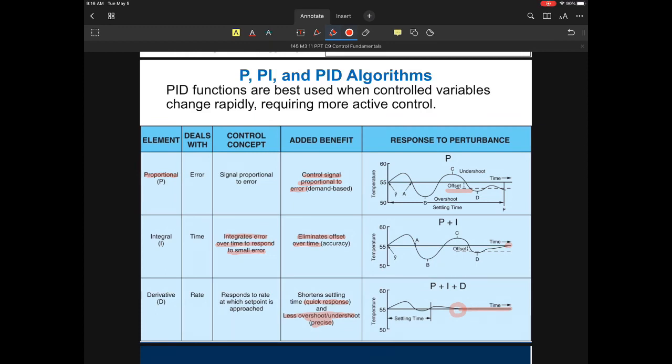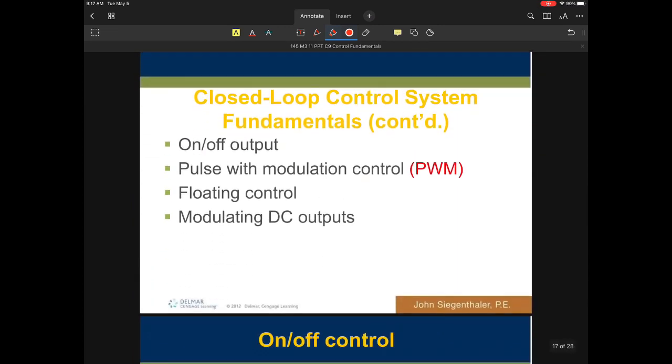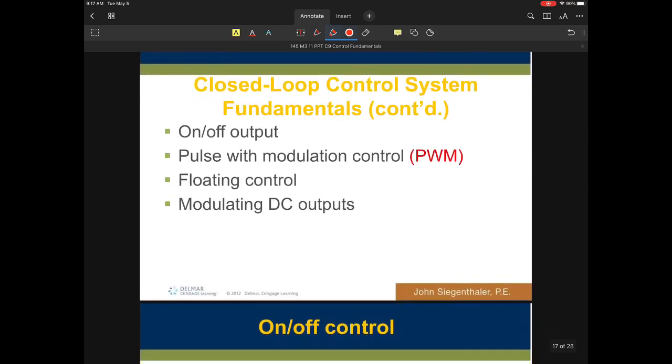It's essentially how much error based on the load. So in other words, as a general rule, if it's colder, in this example, what they're showing here, then I'm going to have an offset that's going to be lower than the set point. And if it's warmer, I'm going to have an offset that's going to be higher than the set point. The only time that you ever really sit completely at set point is when the load and the control variable provide you the exact amount of output that meets what is really needed, based on your calibration.